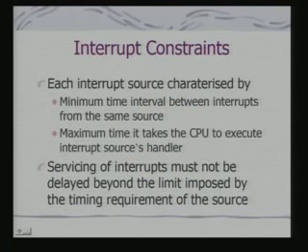And so, each interrupt source, which may be an external source, or in the case of microcontrollers can be peripherals which are on chip, I need to characterize each source by the minimum time interval between interrupts and the maximum time it takes the CPU to execute the interrupt source's handler.